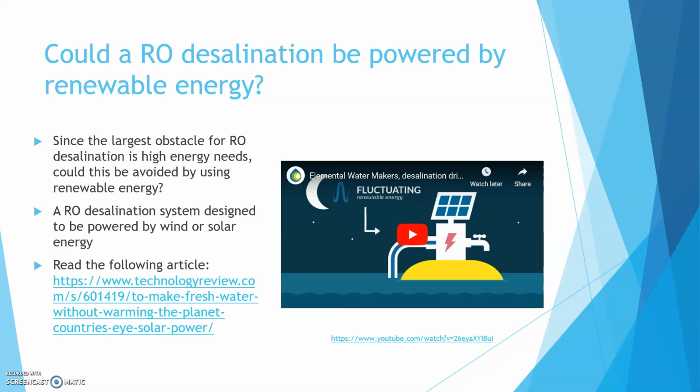One of the primary measurements of a membrane is its square footage. Membranes are available in the range of 350 to 450 square feet of surface area. Semi-permeable membrane was first constructed using cellulose acetate, as we already discussed, but later the industry switched primarily to the use of thin film composites. It is the latest technology in the industry, being placed on top of a substrate. TFC membranes are primarily used today.